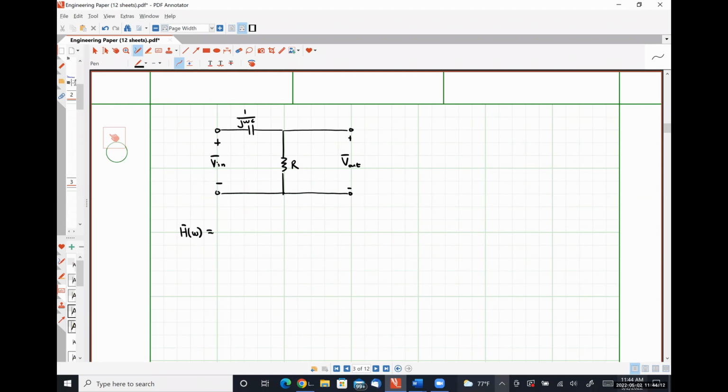Okay, so I'm not looking for my output voltage here, which would include VN. I want the ratio. We're always going to have a voltage divider circuit. That's what all of these things work out to be. So it's always just going to be the element that we're taking the voltage drop over divided by the total series resistance. Always, always, always. So we're going to cut out that intermediate step because there's no point in doing it if it's always going to work out this way. So that's why I stopped doing one too many steps of easy math.